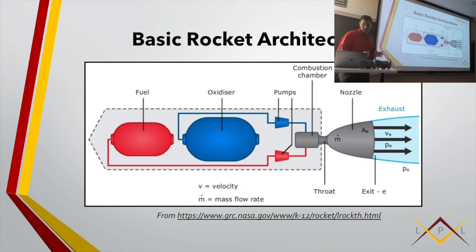This is the basic architecture of a launch vehicle. Going across, you have your tanks, and this would be for a turbopump, which is typically used for launch vehicles. Right now we also have pressure-fed engines, and a pressure-fed engine means you need high pressure gas to push the propellant into the engine. That means the tanks need to withstand high pressure, so the thickness of the tanks needs to be quite thick to hold that pressure, and now all of a sudden the mass explodes.